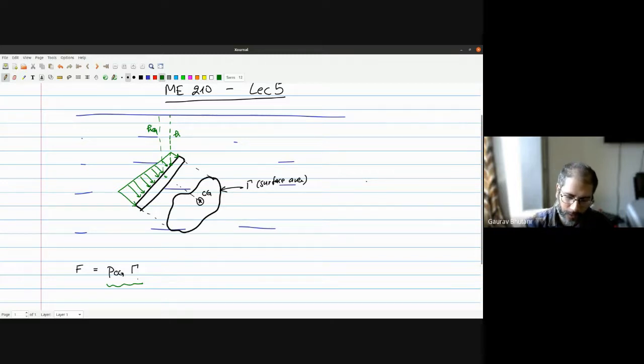Now, if you were to see the distribution of forces like you have here, that's the force distribution. So we can see that it's not a uniform force. Firstly, the force increases as you go towards the bottom side of the body. So what we effectively expect is that we'll have to apply the opposite force somewhere here. If I apply it at the center of gravity, the body will rotate, because the net moment we have is because of a force which is concentrated towards the bottom part of the body.